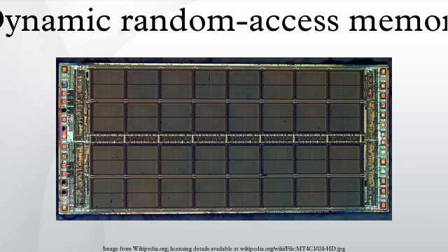and even the premium 20 ns variety is only 2.5 times better compared to the typical case. CAS latency has improved even less, from tCAC = 13 ns to 10 ns. However, the DDR3 memory does achieve 32 times higher bandwidth. Due to internal pipelining and wide data paths, it can output 2 words every 1.25 ns, while the EDO DRAM can output 1 word per tPC = 20 ns.